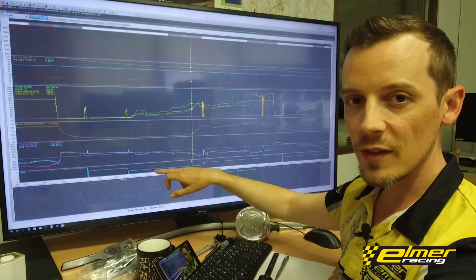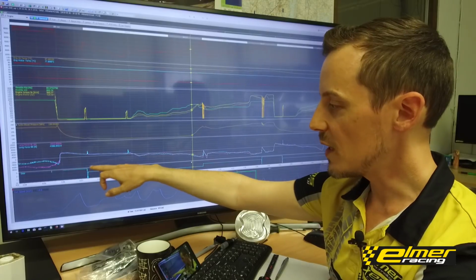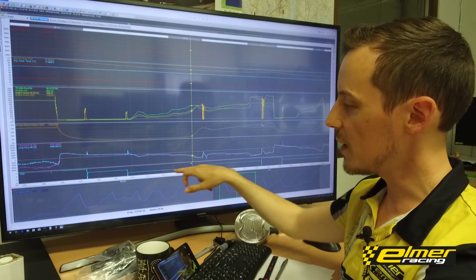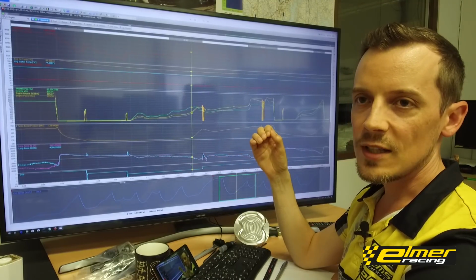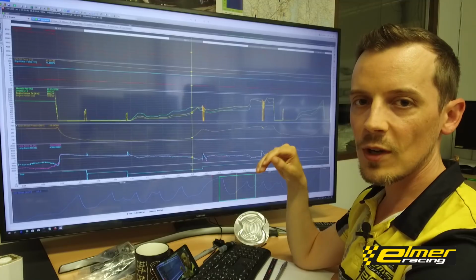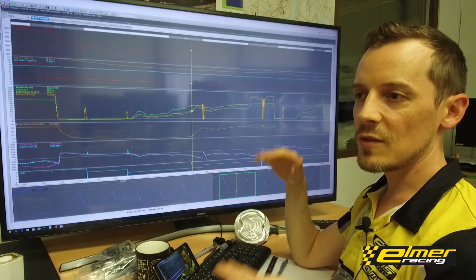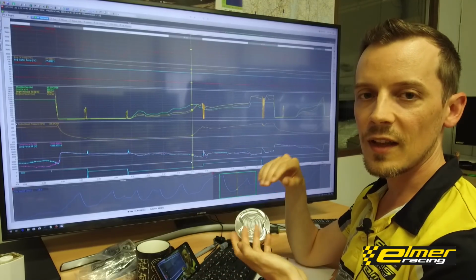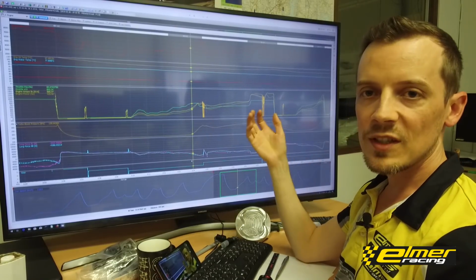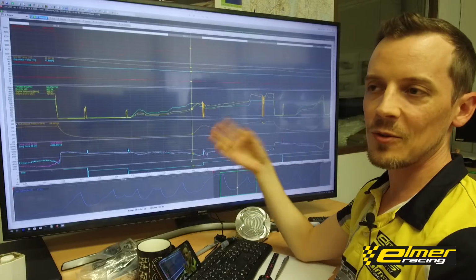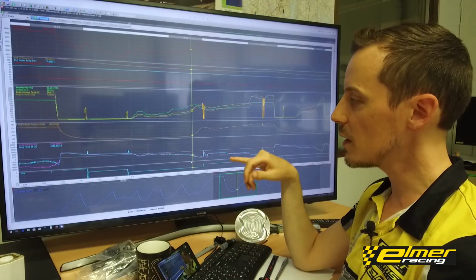So this is into turn 2 at Sydney Motorsport Park. We're basically coming flat out through turn 1, shifting down to gear 2 and then down to gear 1. And this is with slicks, which the car is actually designed for. Racing in the World Time Attack Pro class, we're going to need to use A050s, and the sidewall especially is so much lower that it's not possible to run those at these full speeds. But we want to design the car, of course, to be able to run flat out. So that's what we're using for design criteria and comparison here.